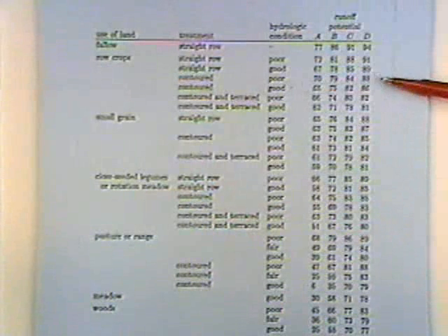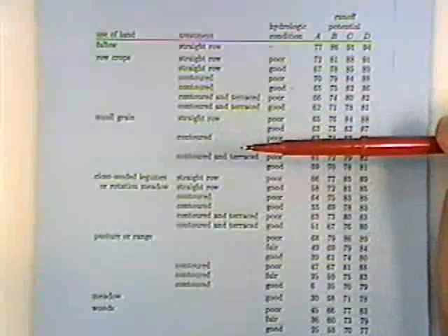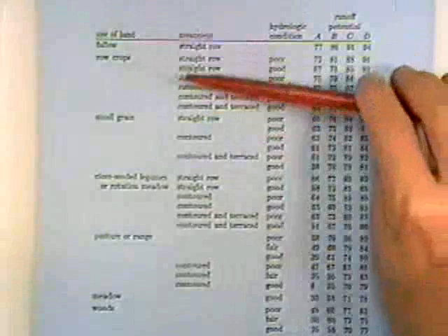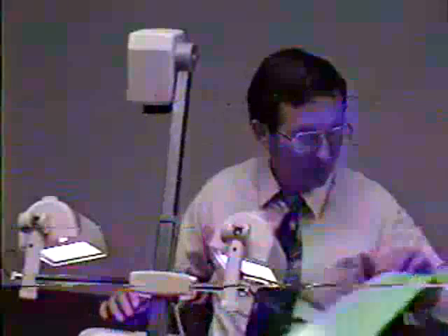And then, in addition to the soil type, the curve number is a function of the land use. And in your book, they do it for agricultural land uses. And in the notes, I also added another extension of this table, which is in many other references that show land uses for urban areas too, residential, commercial, industrial type land uses. And so you can estimate your curve number.